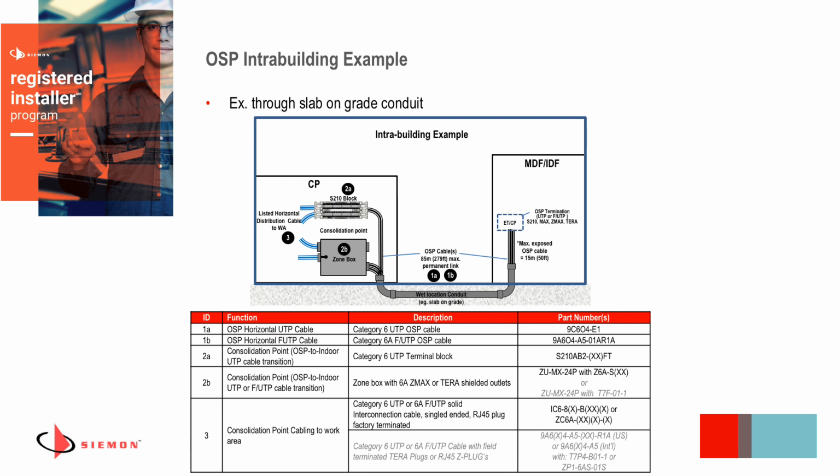And just to talk a little bit about, we mentioned indoor-outdoor cables and OSP cables and where some of these cables might be used. Here's an instance where you might use an OSP type of cable within a single facility. In these instances, you have an OSP cable because you're going into what's referred to as a wet location, which is when you have conduit within the slab of the building where the moisture can build up, and the cable might actually be sitting in a wet type of environment.